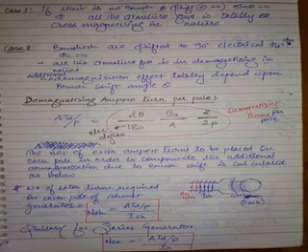In order to compensate this additional demagnetization, additional field ampere turns need to be provided on each pole, therefore demagnetizing ampere turns per pole are calculated.